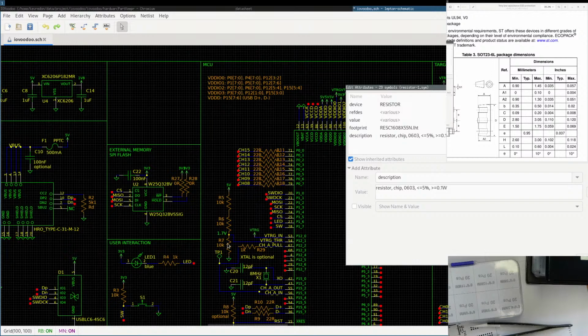These ones are voltage dividers. Here there should be around 1.8 volts. Since it's the same batch, I expect it's the same. It doesn't have to be really that precise. But this one is very precise because I do a lot of calculation on that. This should be at least 1% precise. Oh, I have modified here.